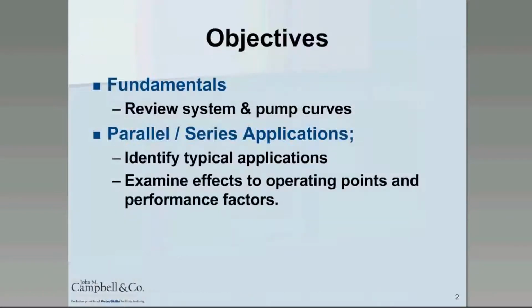So today we're going to be talking about some of the basic theory surrounding system and pump curves, and then apply that theory to pumps that are installed in parallel and series. We'll also consider typical applications for parallel and series pumps, and then we'll look at the effect on performance factors such as net positive suction head, power, vibration. And then when we close out today, we will look at some of the areas of concerns, almost like a checklist of action items to just double check your system.